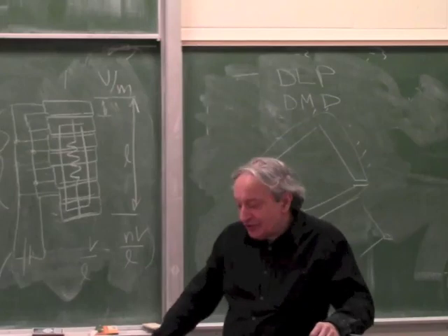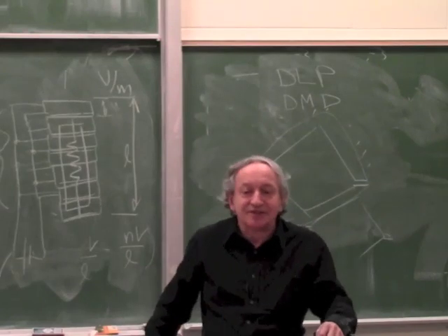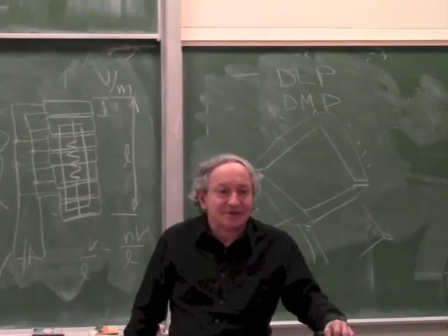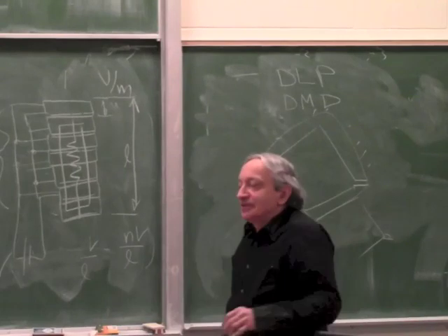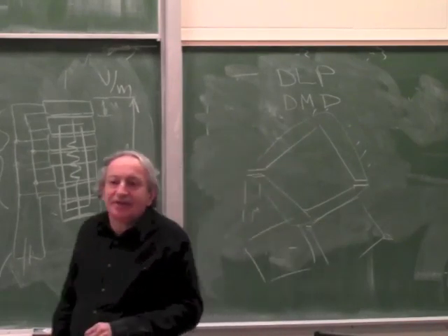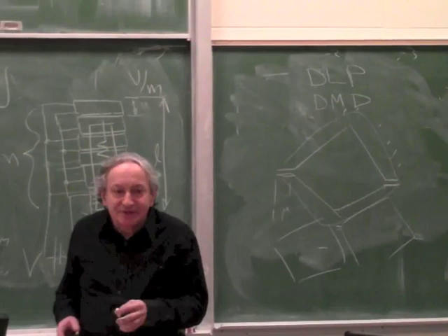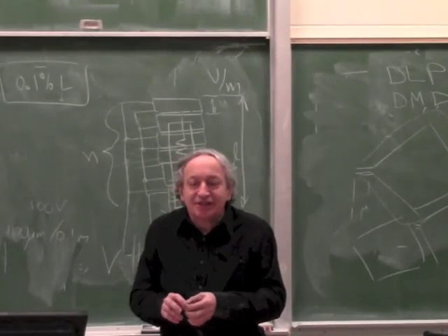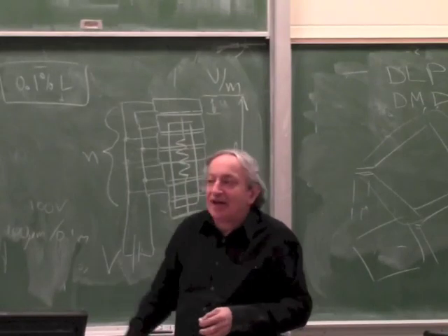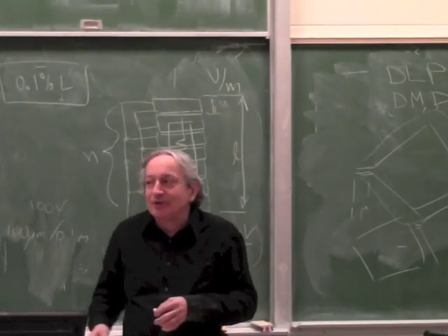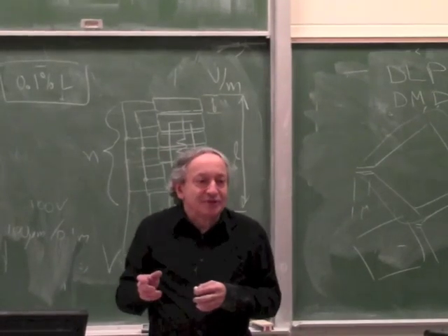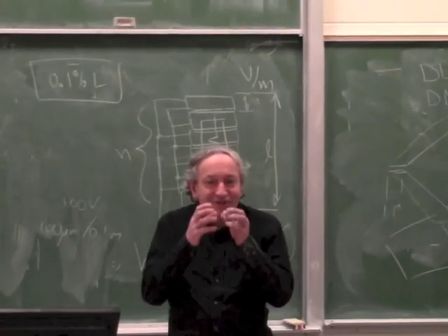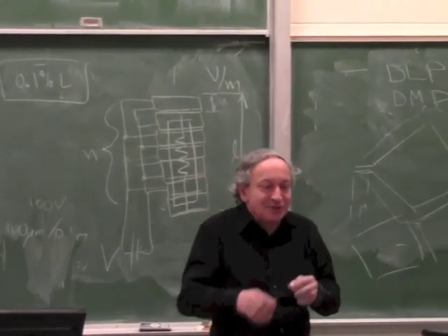So if you have a very confined space and you have to generate tons of force, the best actuators are hydraulic. That's the reason why in a lot of operations where a person has to go into a tight spot, like salvage operations, rescuing people from a wrecked car, or going into a tunnel to rescue people, all the motors are hydraulic. Because in a very, very small package you can put huge power.